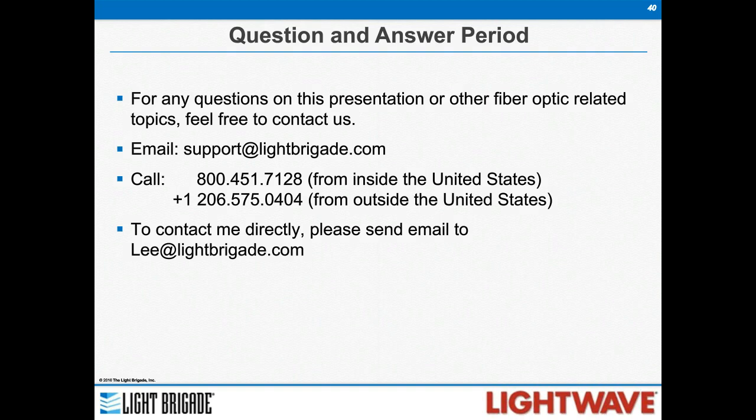So the test reference cord is going to be a short cord, maybe a meter. So the fiber itself has negligible loss. And what it's doing is it's allowing you to test the loss of that last connector in your link by mating to it. So if you reference that out, like they do in a 2-jumper method where you reference out both test cords, you would not account for that last connector in your network. So you would be measuring lower than what the real loss is, because you would be referencing out one of your connections. So unless you're using really long test reference cords, which we don't recommend, that 1 meter of cable is insignificant in your test.